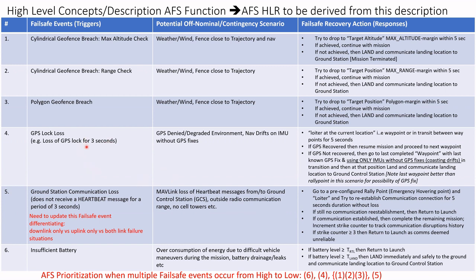Just for the exercise, to go through one of the events, when you have a GPS loss, then the recovery action essentially is for the ArduCopter to loiter at the current location.